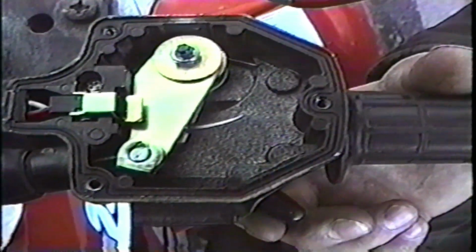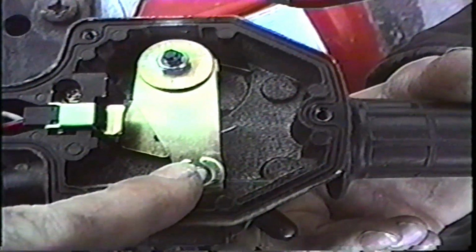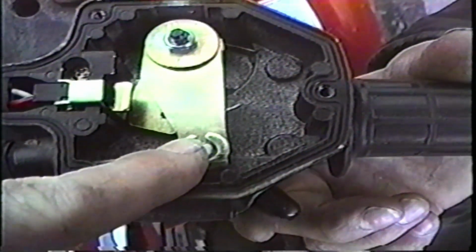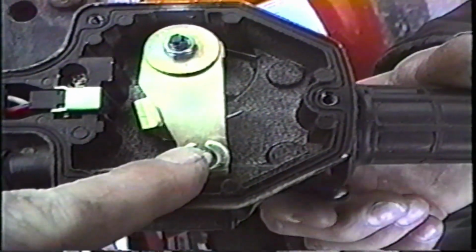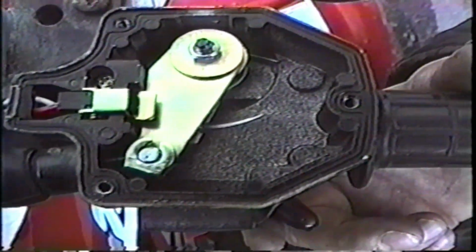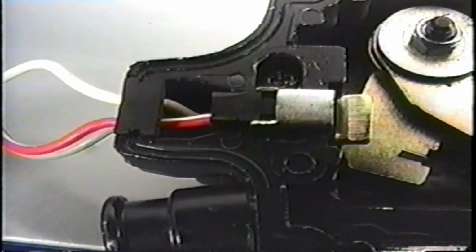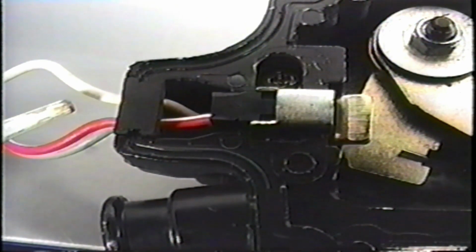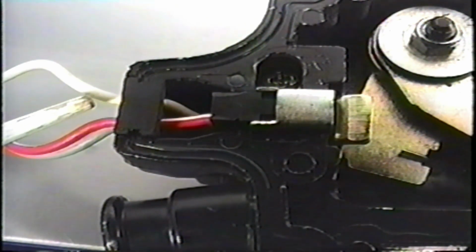On ATVs produced prior to 1994, a spring-loaded throttle flipper pulls against this lever attached to the throttle cable. When the throttle flipper is released, the lever returns to idle and depresses the ETC switch mounted in the throttle block assembly, even if the throttle mechanism malfunctions. A depressed switch will provide battery voltage to the white wire leading to the speed limiter module.